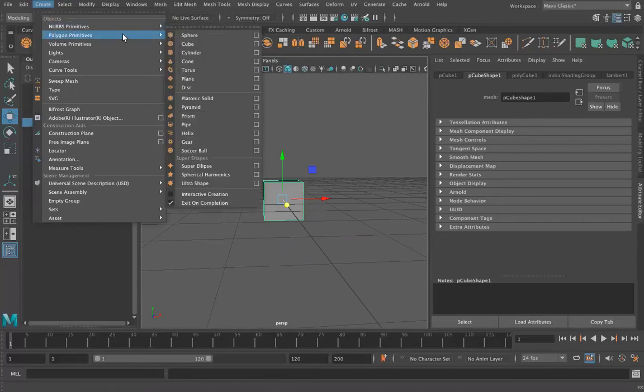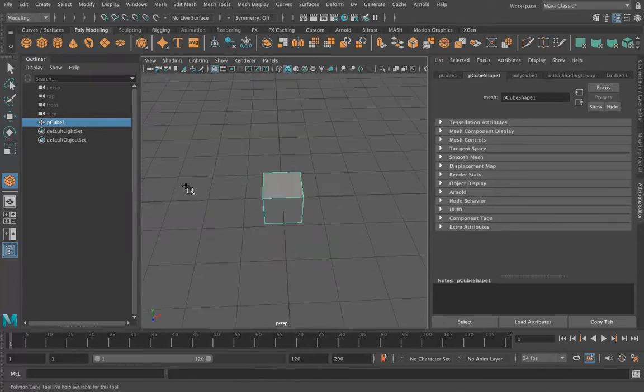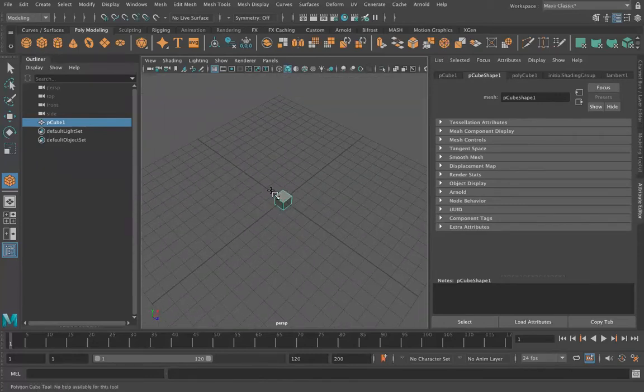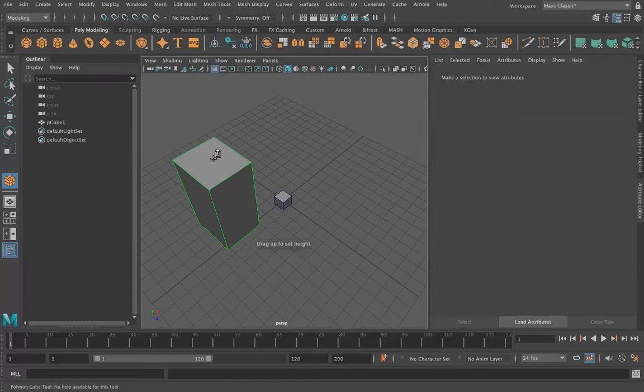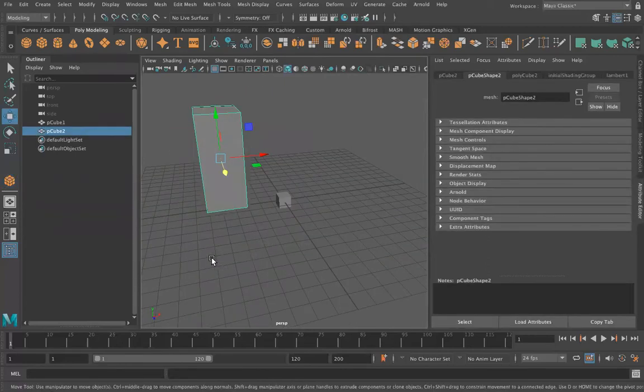And if I go to my polyprimitives here, I have interaction completion checked on. Right now it's checked off. This is how I like it, but I did want to show you that if you have that checked on, then when you go to place a polyprimitive in the workspace or in the viewport here, it's going to pop one on the grid, and you're going to be dragging and setting. You're going to be interactively creating the